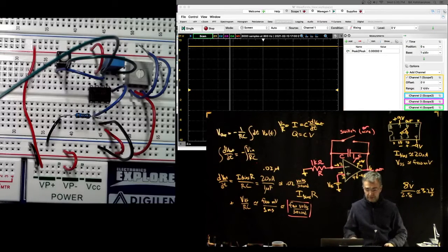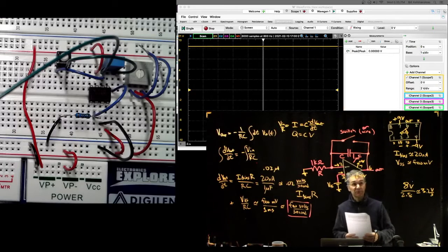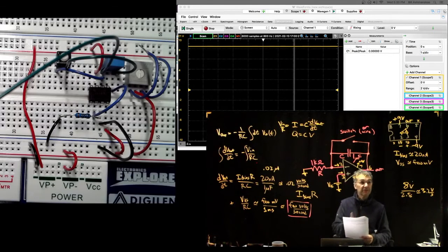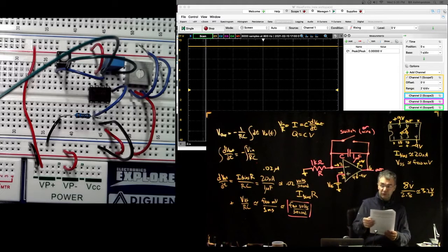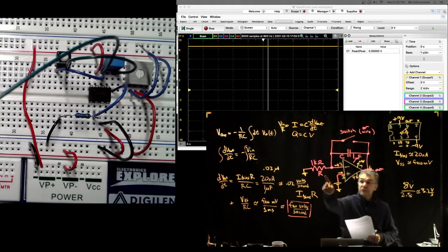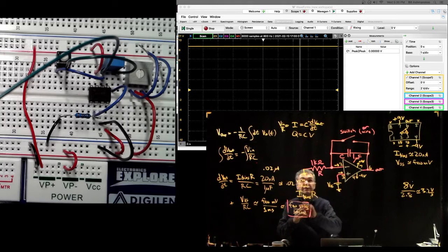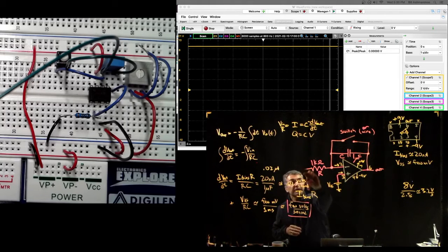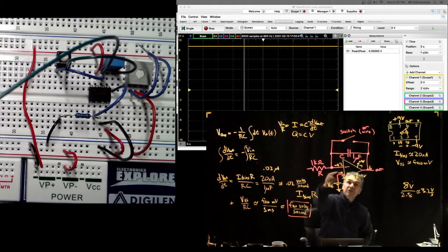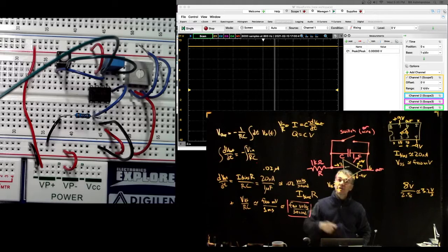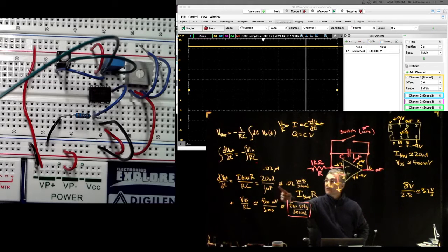Okay, so then the next trick, it takes a little while to puzzle this through, but if you look at the math I did on page 6, you can see me puzzle it through for you. You don't really have to puzzle it through yourself. But if we disconnect this, just let it float, so it's as if we erase this resistor, then Ibias can still charge the capacitor, but there's no longer this V offset over RC term.